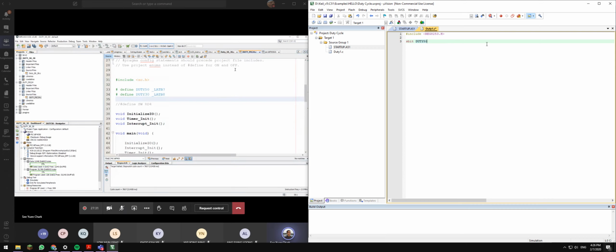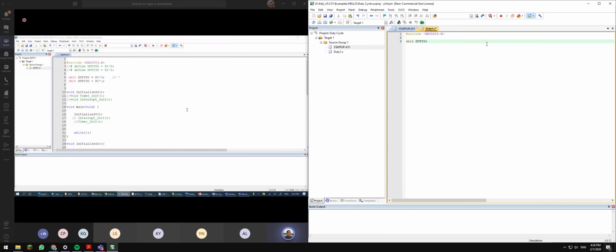So this means that when you migrate to a new microcontroller, you need to identify some fundamental C programming for that particular microcontroller as well. All these things are identified through the microcontroller's C compiler manual. For example, for this one I need the XC8 or XC16 user manual. Is it all right? So in the end, you need to do a lot of reading.